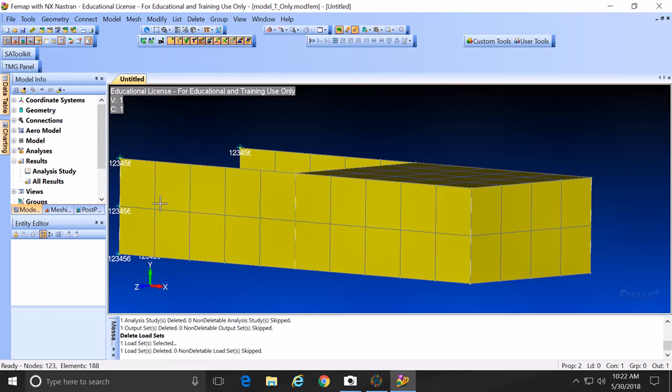Okay, what I think is happening is this: if this is the panel and I apply the load over here, it's just showing that this node is moving by itself and it's not moving the whole panel. So what I'm going to do is take the nodes at the corners. I'll probably just need the ones at the corners. If you want, we can take the other ones, put them all in the middle and then apply the torque. So when it turns, it will be turning the whole cross section at the same time, no? Does that make sense or no?